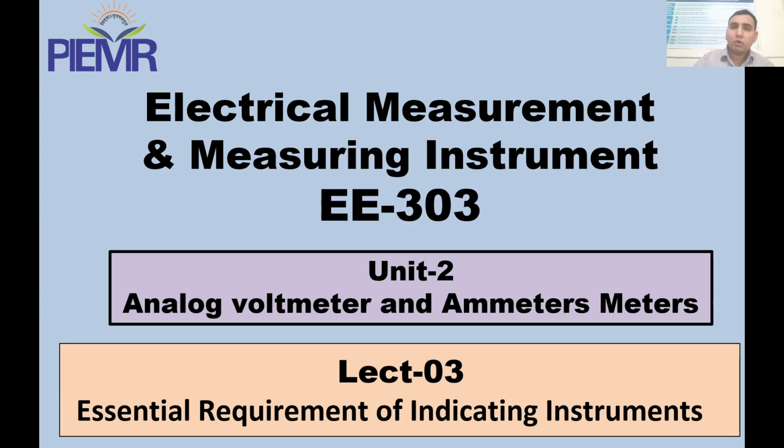One important point: the torque providing the force of deflection for moving the pointer in such indicating instruments is defined in our continuing session, where we talk about how an indicating instrument provides the torque, and how the types of torque provided differentiate PMMC meters, MI meters, and particularly EMC instruments. We also have other torque values, like the torque that moves an indicating instrument backward to its zero position, and the damping torque, which slows down the oscillation of the indicating instrument.